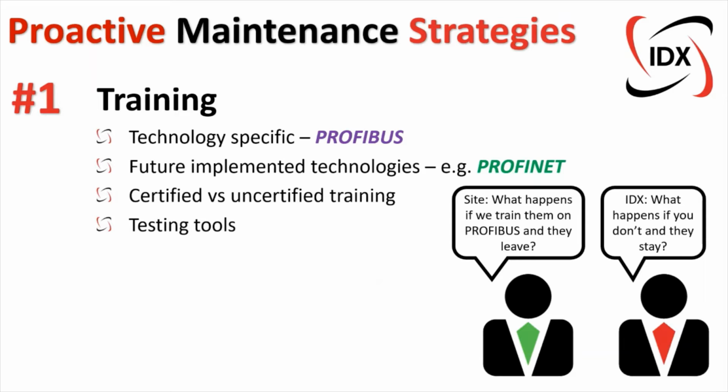So, very important: get the foundation-based training on the PROFIBUS protocol, get the training on the test tools, and understand how those test tools work. It's also very important for maintenance staff to understand how the devices on their network actually operate. The various I/O or field level devices, how to configure them, and how they behave when the devices fail or do certain things.